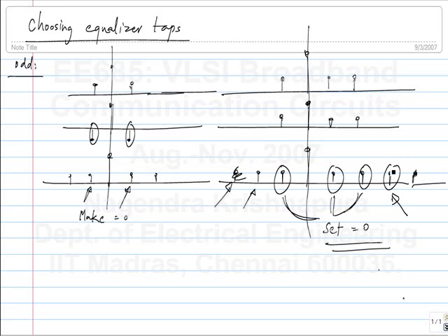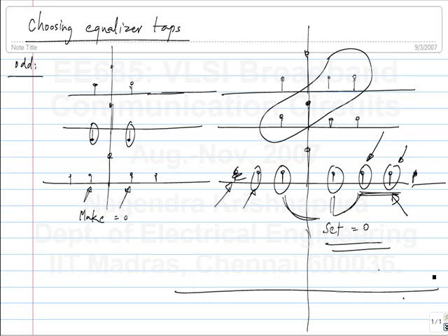Is that, no, this is the product of which and which? Equalizer. You can't make this 0. It's only the choice between these 2. So then I would make this one 0 because this would then turn out to be smaller, I think. So see, you can't make the n tap 0. That's with an even number of taps. Yeah, I had not mentioned this in the class.